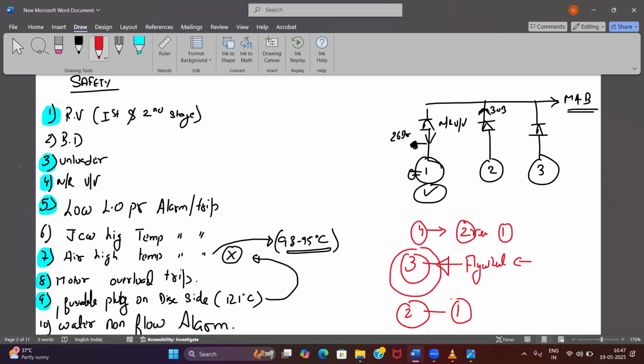So in four stroke engines, you have one power stroke in every two revolutions, right? In every two revolutions of your engine, you will have one power stroke. But in two stroke, in every revolution, you have one power stroke. So there, comparatively, the force required from a flywheel will be less. That's why your two stroke flywheel will be less big than your four stroke flywheel. Four stroke flywheels are much bigger because they have to take care of almost 1.5 revolutions of your engine.